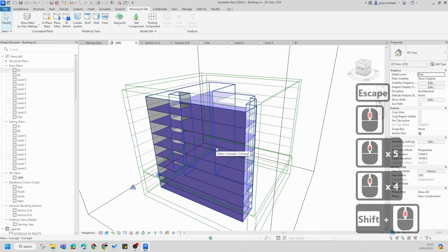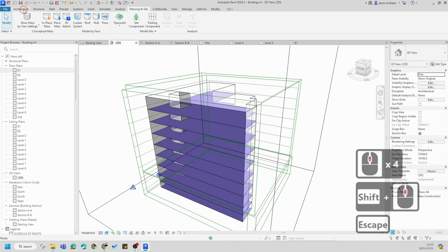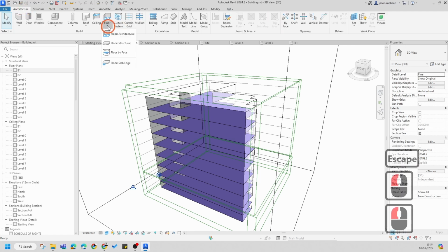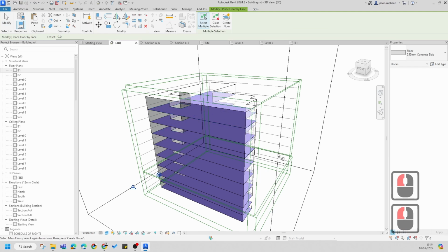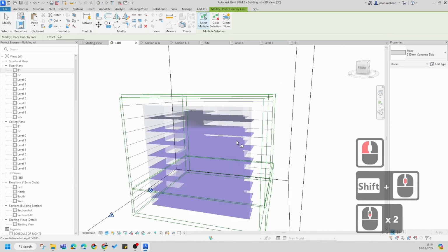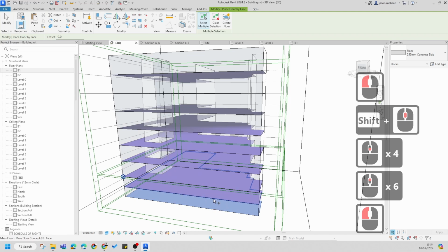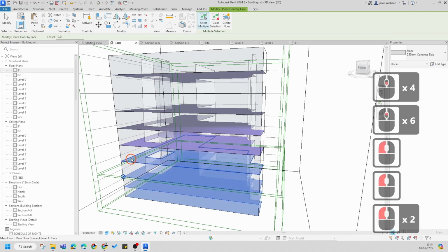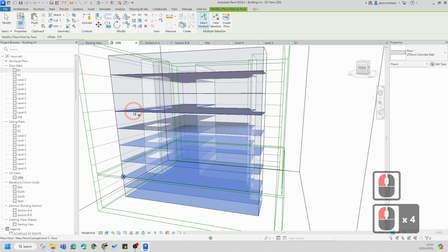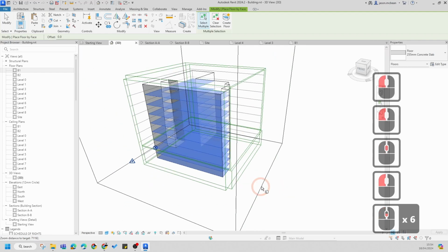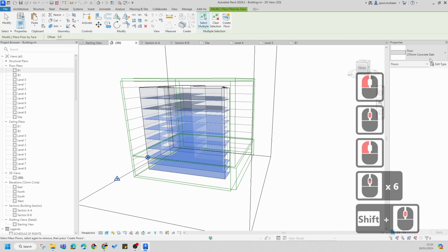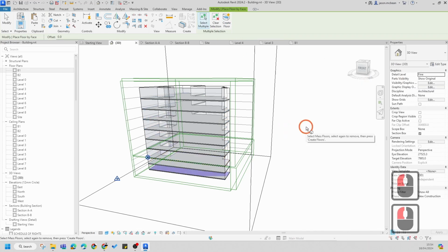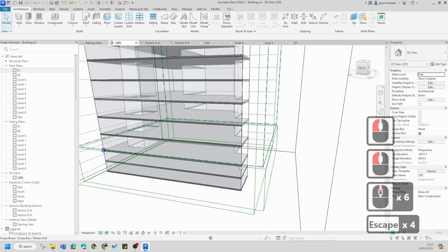So we're going to use a combination of 3D and 2D. Now, in the Architectural tab, if you go to Floors, and you're going to say Floor by Face, now you'll see that your mass, because you've used the mass and you've assigned the floors to the mass, I can now quickly go and select all those floors in the mass very, very quickly. And what it'll do is it will create, so just like that, I'm going to go and assign the 255 concrete slab to those, create floor slab. Okay, good. Now you see it's created these floor slabs.